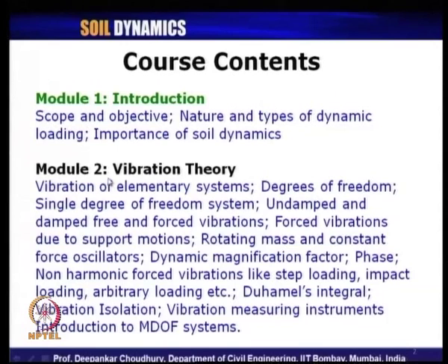In the second module, which is on vibration theory, we will cover vibration of elementary systems, degrees of freedom, then single degree of freedom systems, undamped and damped free and forced vibrations due to support motions, rotating mass and constant force oscillators, dynamic magnification factor, phase, non-harmonic forced vibrations like step loading, impact loading, any arbitrary loading, etc. Then the concept of Duhamel's integral, then vibration isolation, vibration measuring instruments, and finally, an introduction to multi degree of freedom systems or MDOF systems.